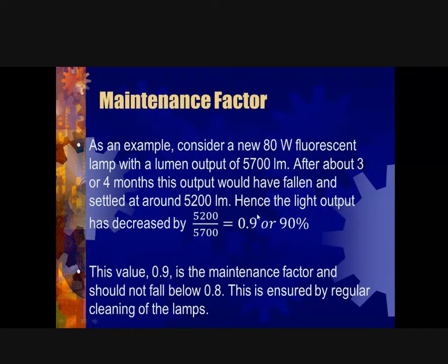And sometimes, even for the lamp itself, what you have to do is actually replace the lamp. The lamp might not be blown, but after years of using the lamp, the efficiency and the maintenance factor is very low, and then it's better to replace the lamp, have a good quality in your home or your office space or your facility, rather than maintaining it at a low maintenance factor and affecting a person's eyesight, right? So it's very critical to understand what the maintenance factor is.